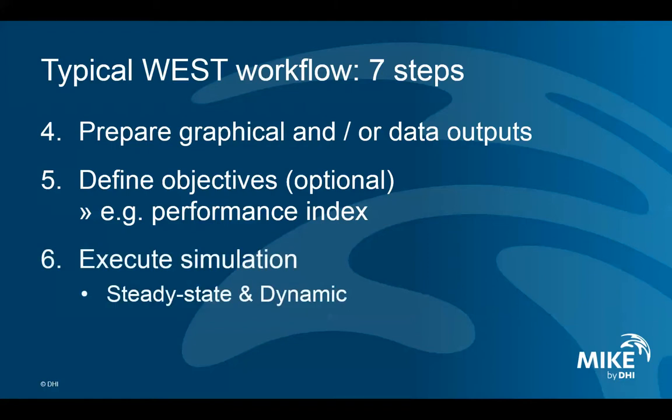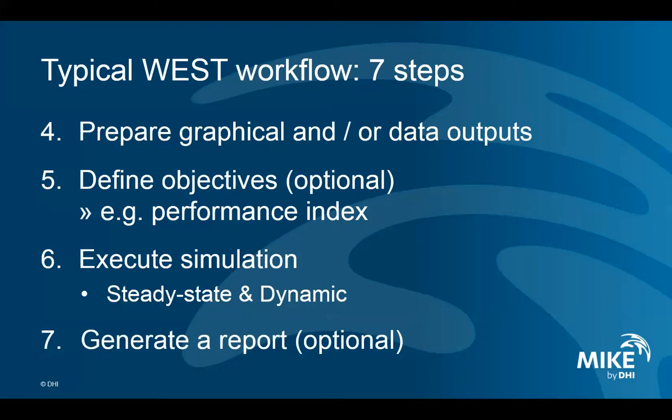I will finally execute the simulation, actually 2 simulations. First, a steady state simulation to effectively initialize the system. Then the end state of the steady state will be used as initial state for the dynamic simulation. And finally, I will run the dynamic simulation. Seventh and last step, also optional to some extent, I could generate a report of the project and save it as a Word document.